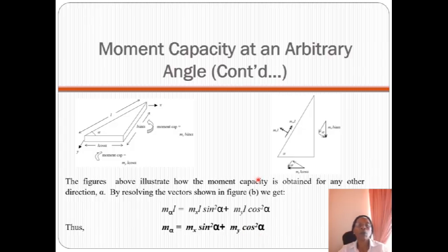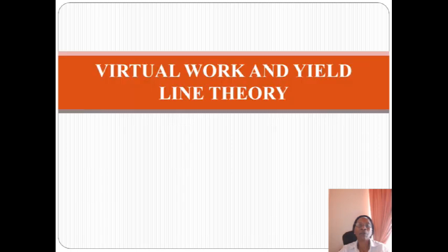I thought it's important for us to get that right from the word go, so that when we are thinking about the moment resistance of a slab due to reinforcement, you look at it from different directions. And remember, this moment capacity is the one that will be used in design.